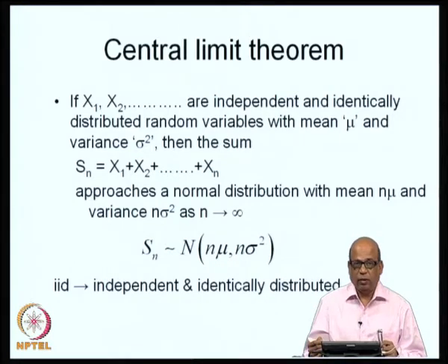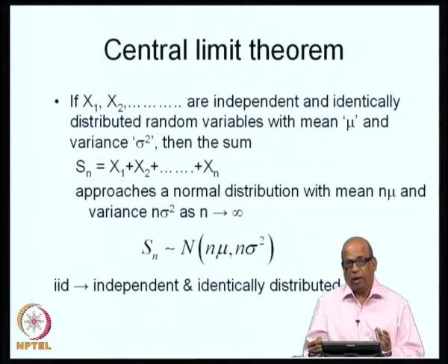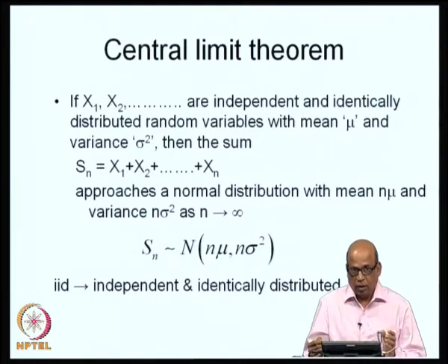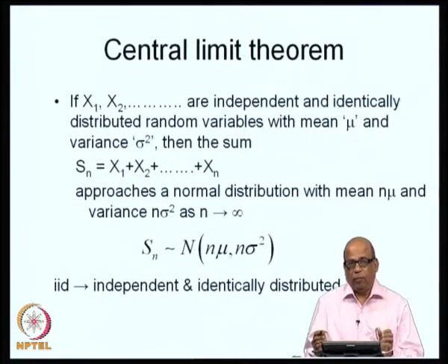If we consider the stream flow in month June as having been constituted of several random variables, in this particular case 30 (or 31) random variables, X1 plus X2 plus X3 etcetera, where Xi's are the stream flows in the ith day. So, the monthly stream flow can be looked at as a sum of daily stream flows in that particular month.